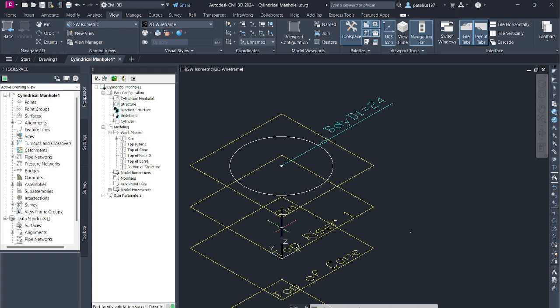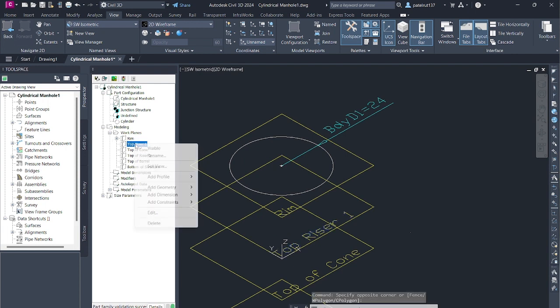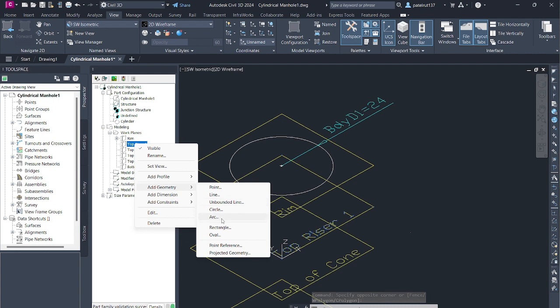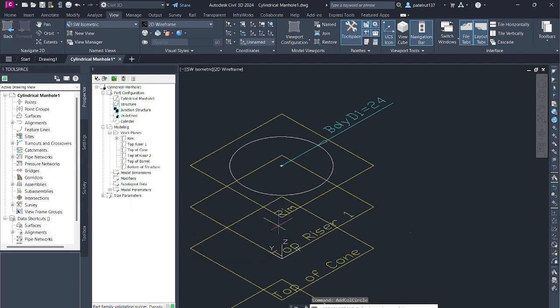Save your part. Additional customizations can be made to the geometry of a manhole such as this one using the principles learned in the vault structure tutorial exercise, as well as other part building exercises. Exit the Part Builder utility. Click the small X in the upper right corner of the Part Browser. The Part Browser is the left pane portion of the Part Builder application window. If you are prompted to save the part, click Yes. Part Builder closes.